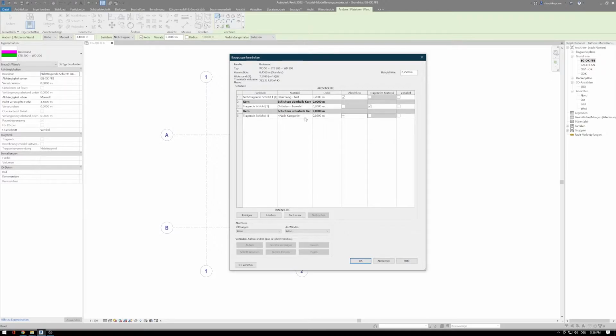And the material has to be same as Dämmung Hard, which we have above. So instead of going to the material browser, I just come here, Control C for the copy. I copy it. I select the nach category and paste. When the name is same, it selects the material automatically, so you don't have to go to the material browser. It would save you a lot of time if you have lots of materials installed, and the material browser can be a little bit laggy.